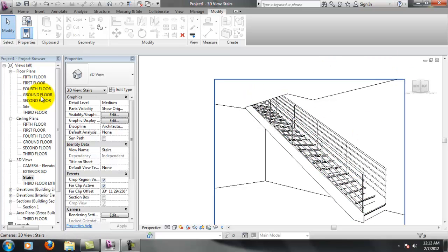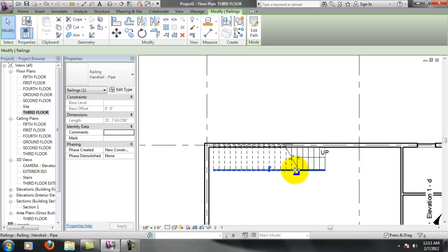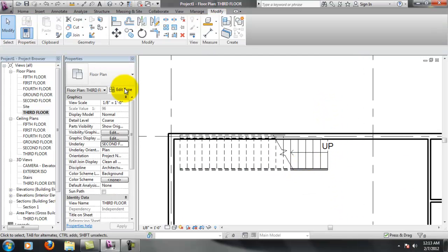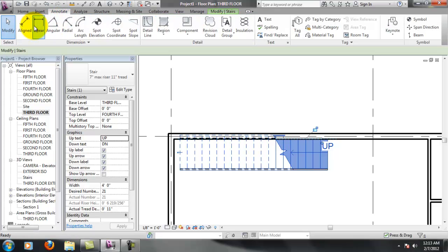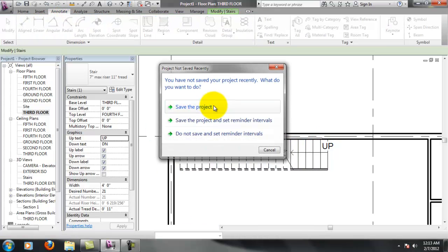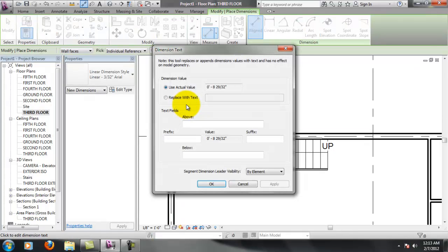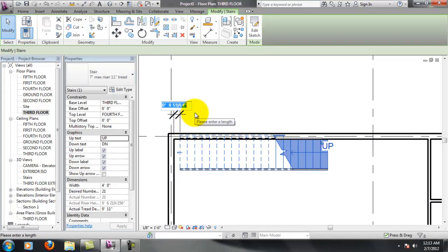I would have to add railings obviously on the top if I was going to do that, but that allows you to pretty much place this thing wherever you want. Now it's a little too close to that wall at the top, so I'm going to make that modification now. Oops, got a hold of the railing there. The best way to do this is probably I need to unlock this from the wall and annotate with a dimension from there to there, and I'll just make this something like 4 feet.